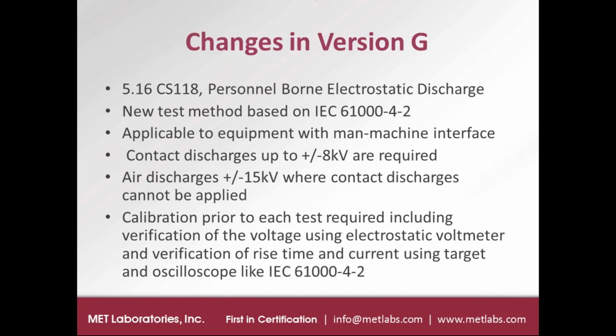So you discharge your stored electrical charge to the chassis of the car, or the car to you. And it stings a little, but most people don't realize that discharge usually is in the range of 2,000 to 15,000 volts. It's a very low current and a very short duration, so it's not damaging or lethal in any way. But it is a very high voltage, and it can be very damaging to electronic components, digital components. So this new test method is based on IEC 61000-4-2, which is an old and maintained ESD standard that has a very well-defined procedure for the test.